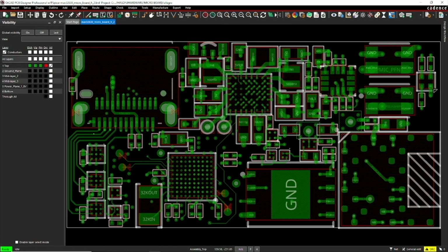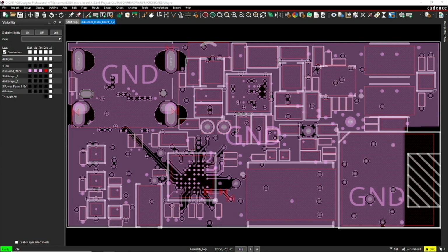All right, I think we covered enough in general about the top upper layer. So let's move on. Next, we move to the ground reference layer. The overall strategy for any voltage reference plane is to retain as much copper as possible so that the plane has as low an impedance profile as possible. Why do we care about impedance being low on the reference plane? Because the net on that plane serves as a reference point for all other signals and devices. If the plane has noise and voltage fluctuations, it starts to become a poor reference.